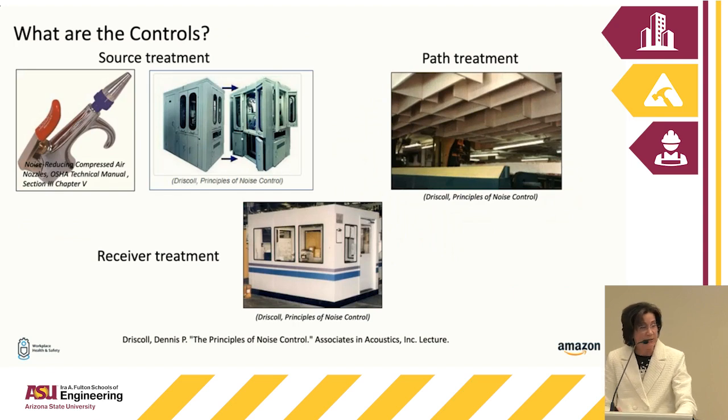So it then comes down to how to control the noise. Source treatments are really the preferred option. And I only put one small source treatment up there in the upper left of the screen, obviously, because they're so complex that even if you put it in, you wouldn't be able to visualize it. But if you can't do source treatments, if you can't quiet the machine, for instance, and the noise being emitted from the machine, you have to figure out how to use path treatments.